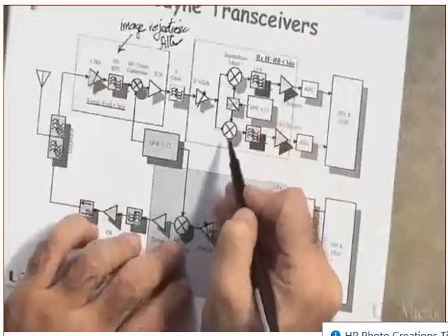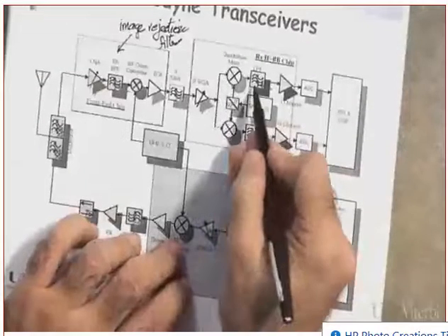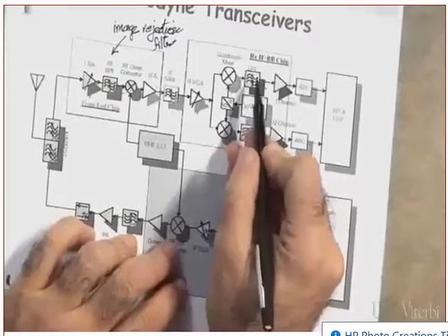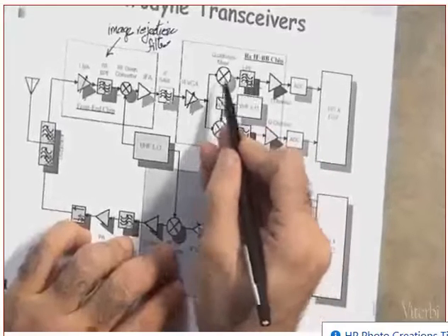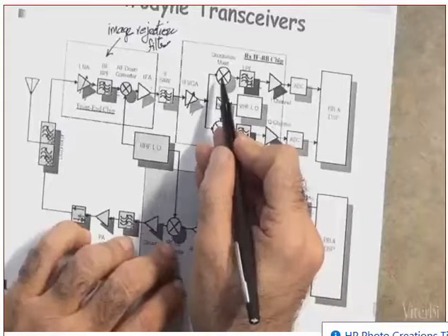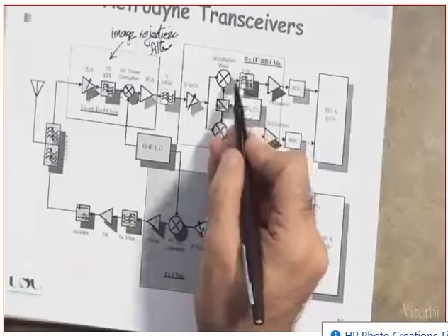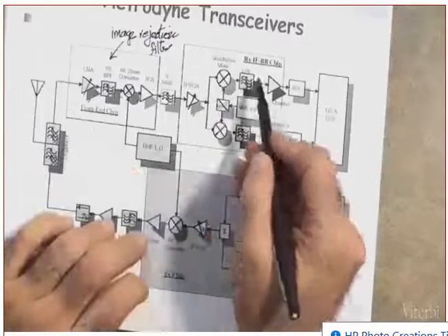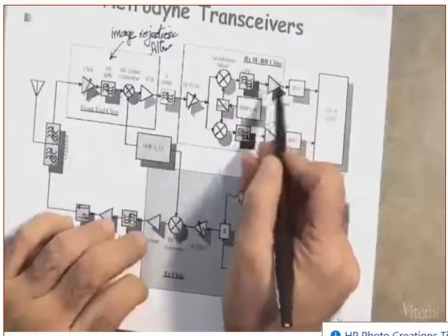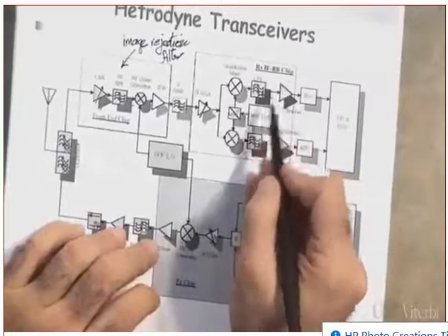Okay. So this one here, again, is the demodulation. This low-pass filter, why do we need a low-pass filter here? We need a low-pass filter because the mixer is going to generate two sides. Clear? We need to just keep one of them. Are you following me on that? Okay. We need an amplifier just for the audio level. This is for the audio level.